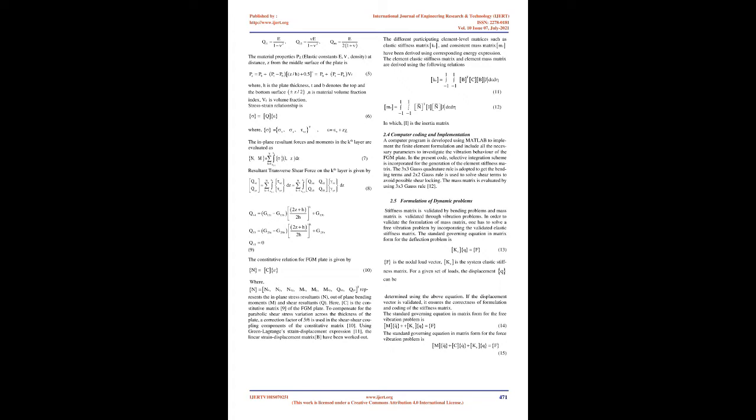plates. Further, we observed that many authors could model such problems only with a stepped variation in material properties instead of continuous variation. This would have happened because of the limitations of the commercial software available. In this context, we felt that Matlab code could be used for tailoring the continuous variation in material properties in FE modeling. Hence Matlab code was developed for vibration analysis of FG plate.